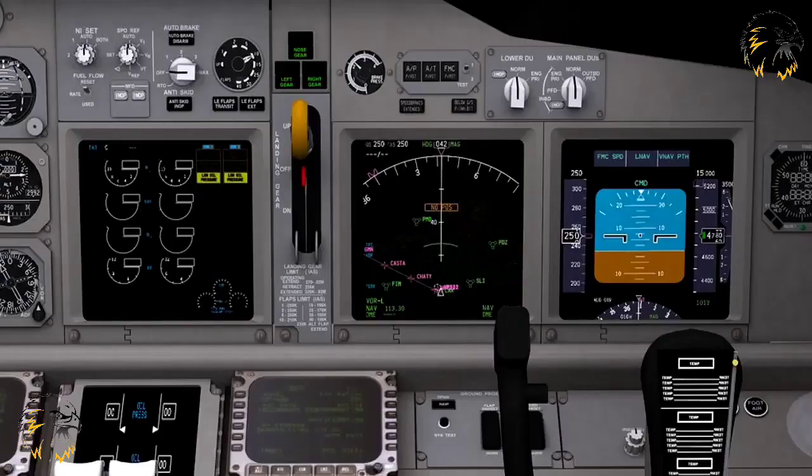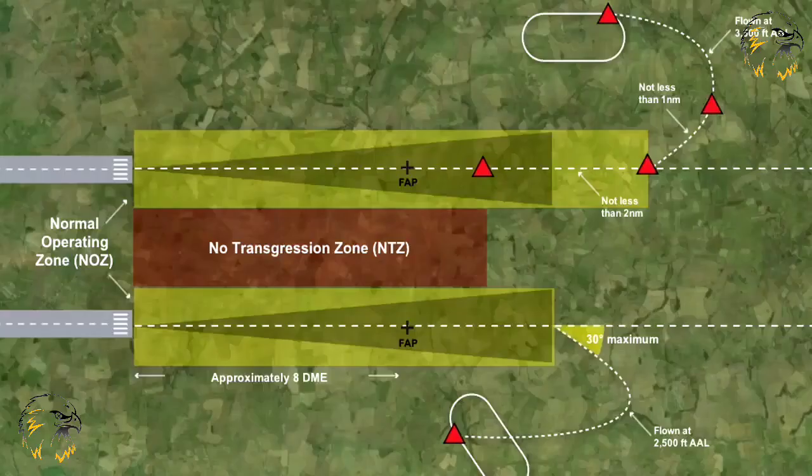To conduct parallel approaches, aeroplanes must be fitted with the normal IFR avionics, including full ILS or MLS capability. Where independent procedures are in force, all aircraft are to be advised accordingly on initial contact with approach control. Regardless of weather conditions, all approaches are to be radar monitored by radar controllers specifically dedicated to that role, using